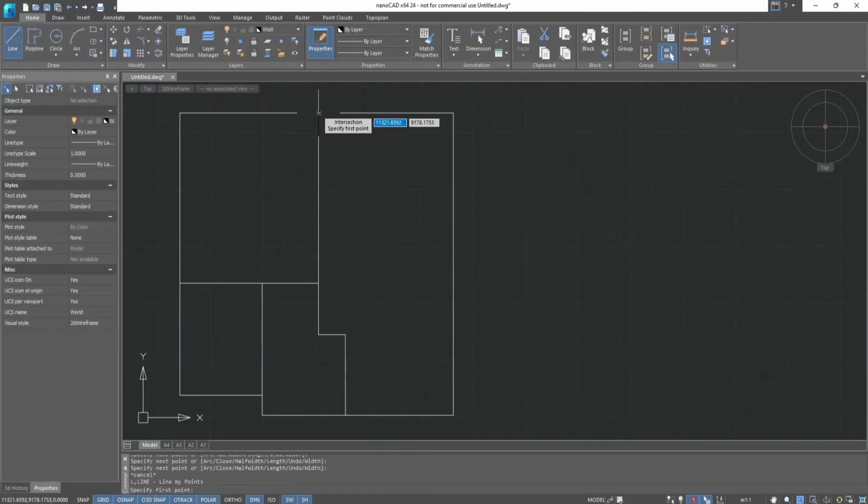In order to position the beginning of the segment further than the endpoint anchor point, you need to aim at the point and start pointing the mouse in the right direction. Then a green dotted line will appear, after which we can enter the desired indentation using dynamic input and continue drawing. 850 millimeters is a loggia.